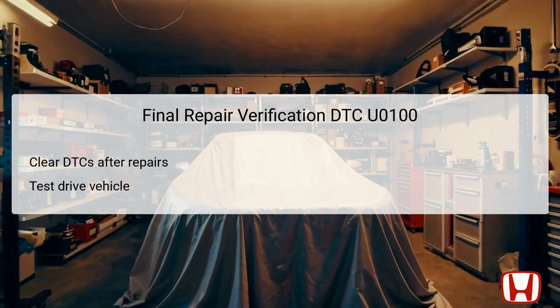Post-repair verification is a vital part of the troubleshooting process for DTC U0100. After resolving any identified issues, including repairing or replacing faulty components, the next step is to clear the stored DTCs using a diagnostic tool. This process resets the vehicle's onboard computer's fault memory, allowing it to establish a fresh data log during normal operation. Following this, a test drive under varied conditions is recommended to monitor the vehicle's performance.